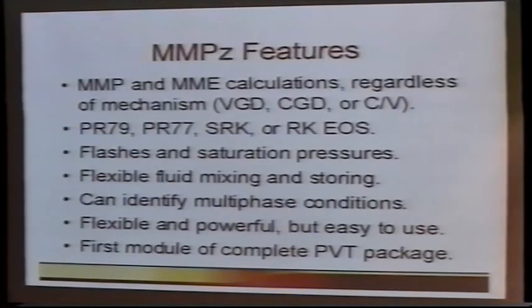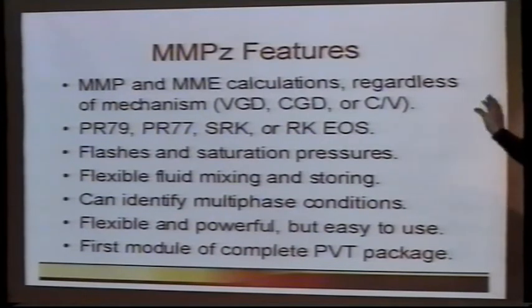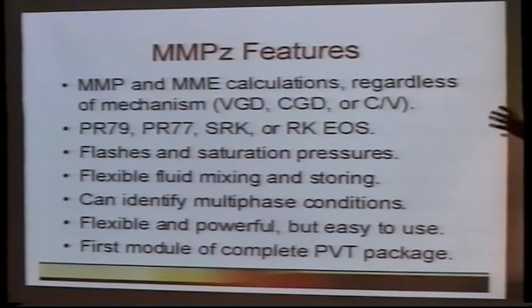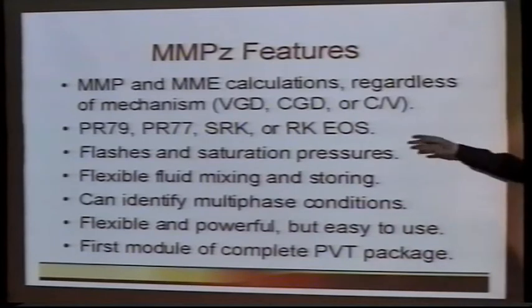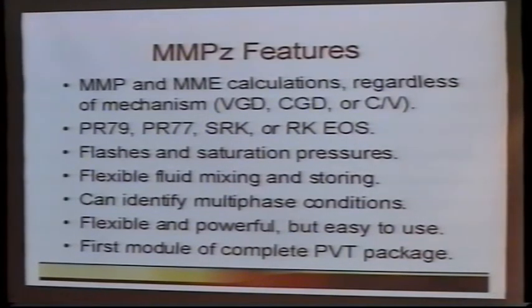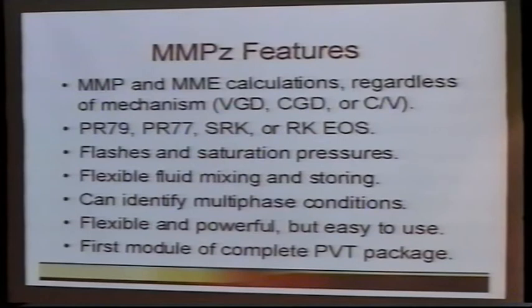All right? Now, besides the MMP and MME calculations, which can be done regardless of mechanism once again, whether they be vaporizing, condensing, or mixed, I've also built in many other features. It can use any of these 4 equations of state. You can also do flash calculations, saturation pressure calculations. You can mix fluids and store them in a very flexible way. It can be used to identify multi-phase conditions.